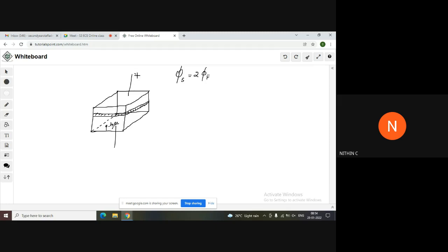So we are going to apply Vg. While the value of Vg is less than 0, at the interface of oxide and semiconductor, accumulation is happening. So when Vg is given less than 0, at the semiconductor-oxide interface, we will have an accumulation of holes. Now we are changing the value of Vg, and finally when Vg is increased to a value much greater than 0, then we'll have strong inversion if this condition is satisfied.